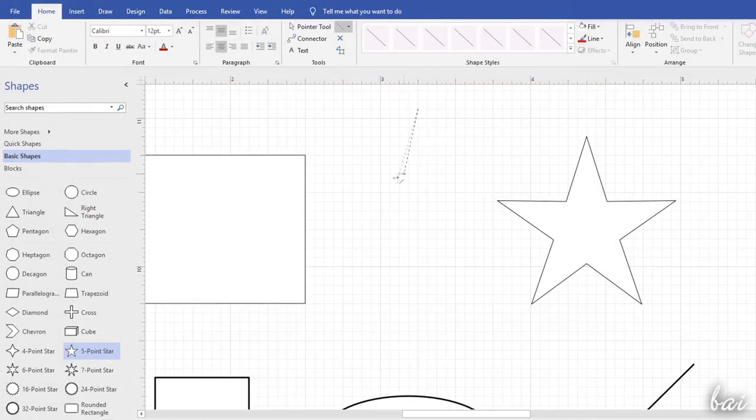Snappings are used to place your cursor directly on grid points, shape contours and vertices when it is close enough. Guidelines are used to draw and align objects through precise directions. You can ignore all these drawing aids by holding down the Alt key.